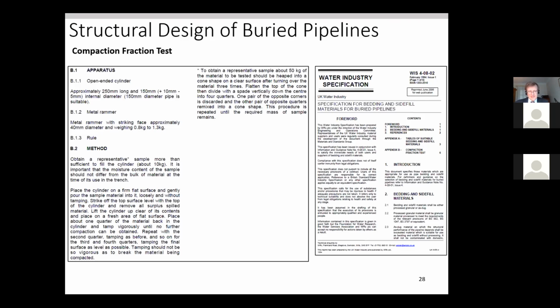Greg came back after your last answer. I think we probably covered it, but he said, sorry, I meant the rigid, semi-rigid methods of structural design for pipelines, which currently use assumptions for determining the native soil properties. I think you probably have covered that now. We're still on Spangler, and you're still guessing for those. You do a range, and it informs a judgment, and that's the approach. It's not a definitive answer, it's a judgment call that has to be made as to which way you go.